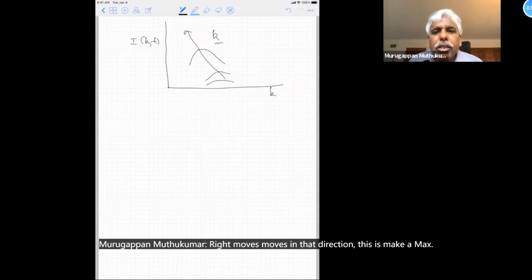The intermediate regime is called the Lifshitz-Slyozov regime, the condensation-evaporation mechanism, which we'll talk about later, probably in the next lecture. And there's also a negative one regime, called the CGR regime. It's dominated by hydrodynamics. So that's the general picture of how the phase separation takes place according to the spinodal decomposition mechanism.